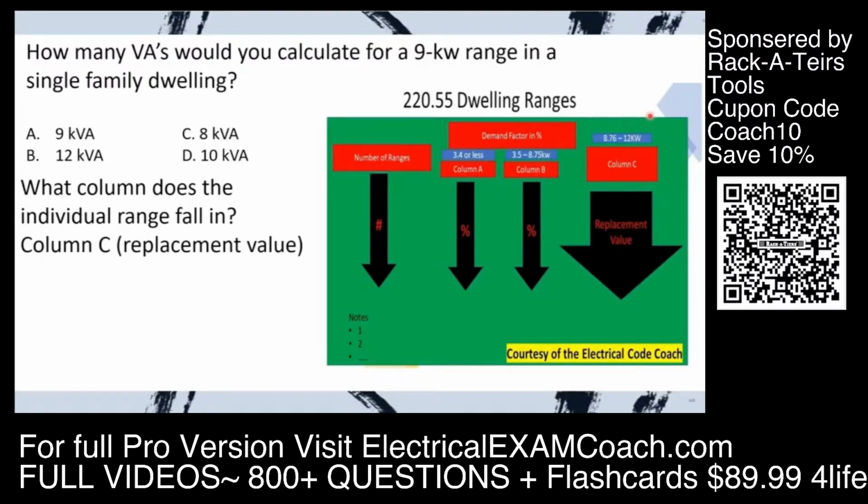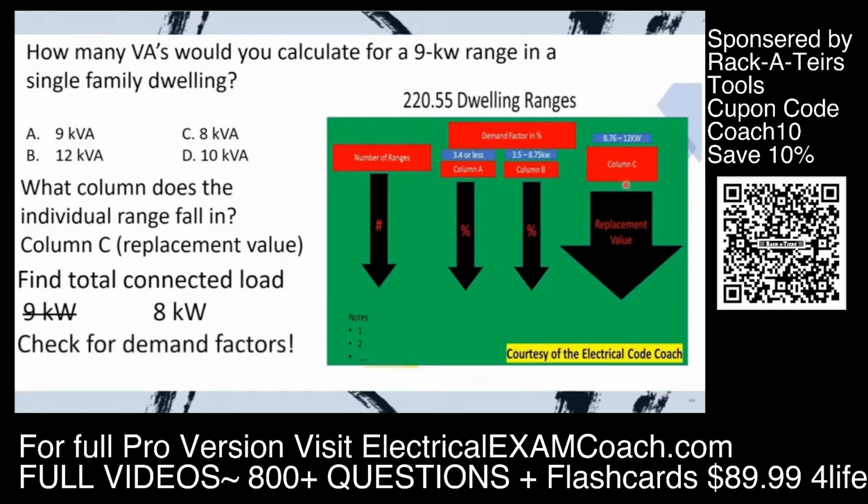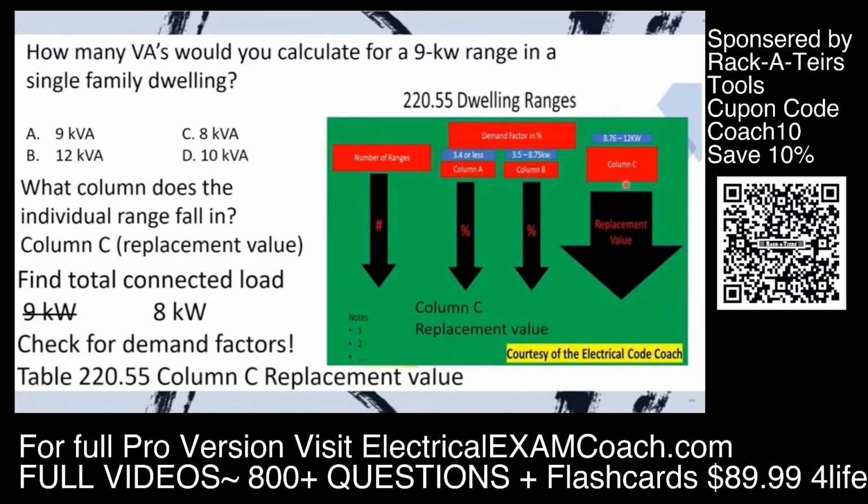Now let's find our total connected load. On the left-hand side, we're going to find our number of ranges. In this case, it's 1. Then we're going to cross all the way over to column C and find that our replacement value is 8 kW. Then, just to stay in practice, I want you to always be familiar with checking for demand factors. But in this case, in table 220.55, column C is a replacement value. It is not a multiplier, so we're just going to select C. Great job.